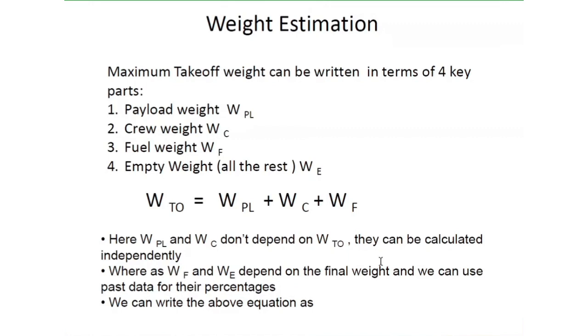Or if you are told you have to have a passenger aircraft with 100 passenger payload, then it is a little bit of approximation. So you assume that every passenger is 80 kgs mass, and every passenger is allowed some 20 kgs of baggage. So 80 plus 20 is about 100 kgs. You can add another 10 kgs for the consumables he will probably be using, like food, water, and the chair and all that. So 110 per passenger. So 100 passengers will be 110 into 100. We will get the actual numbers. I'm just giving you this so that you understand where we are going.